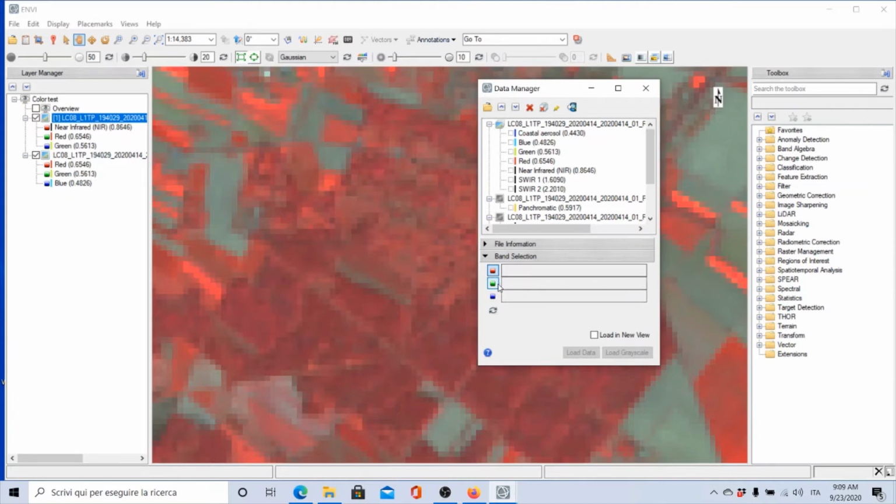So if I wanted to have the vegetation green, you see I'm moving to the green channel here. And what can I do here? Taking into consideration the spectral signature of the vegetation, I'm associating to the green band the near infrared band. Okay, and what can I associate to the other bands? For example, to the blue band I can associate the green original band, and to the red one, for example, the red band. All right, so I'm associating to the RGB red, near infrared, and green, okay, in this way.